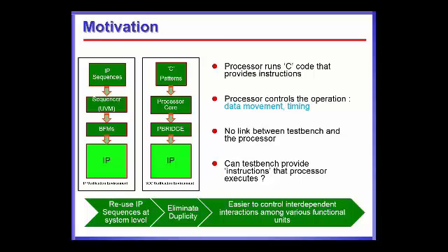Now, this particular execution flow for SoC, or designs with a processor, has some drawbacks. Because we lose the controllability and flexibility that a language like SystemVerilog and a methodology like UVM provide to control the data movements across our design. Because of that, typically SoC verification is limited to a few simple tests targeting some data paths, but to verify some parallel execution among different IPs and their interdependent interactions, it becomes a bit difficult.